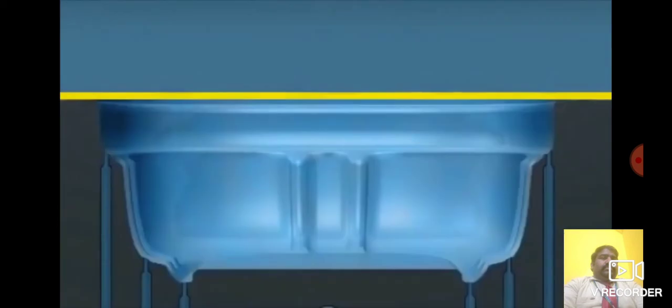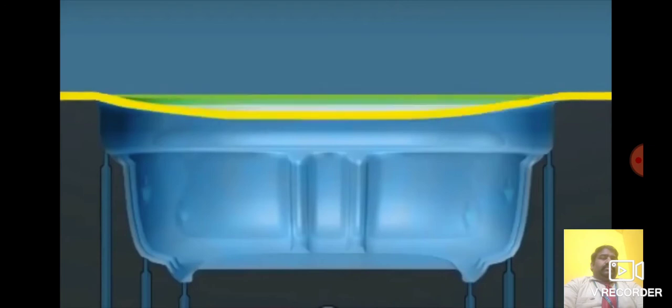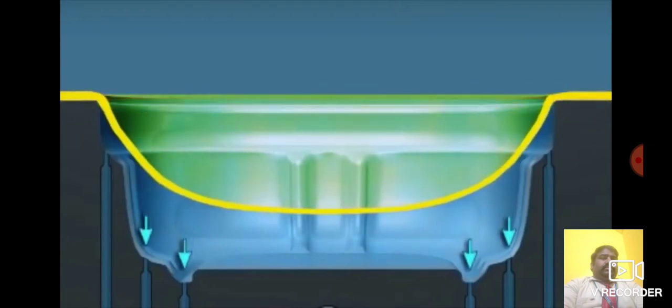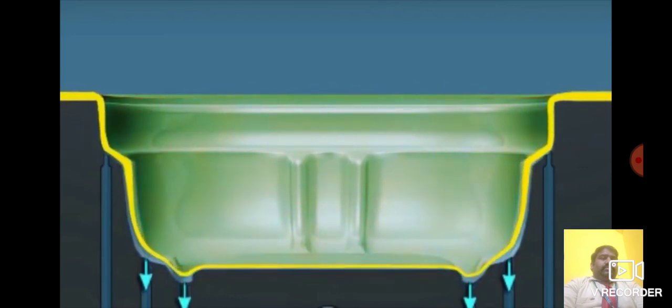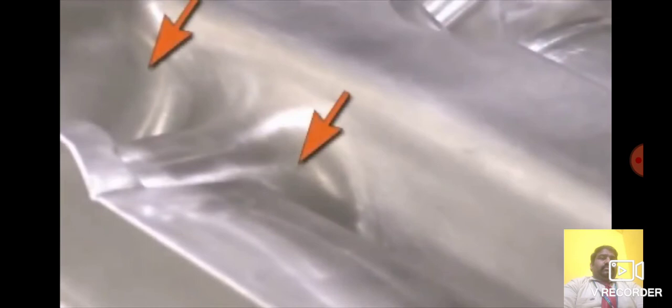When the sheet is sealed against a mold surface, air under the sheet is trapped. Using a vacuum to remove the air forces the sheet against the mold surface. The air under the sheet leaves the mold through vents. To remove large amounts of air, the mold has gaps in the assembly. Drilled vent holes are used in locations where small volumes of air are likely to be trapped.